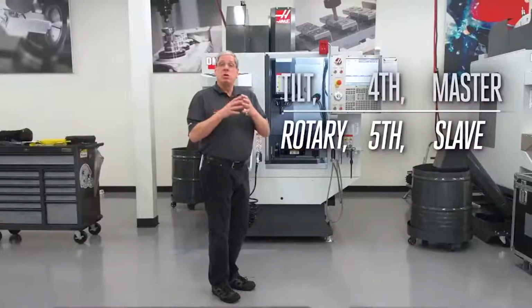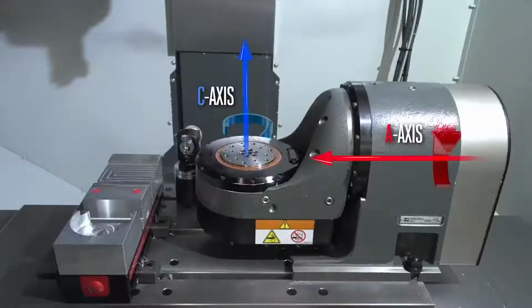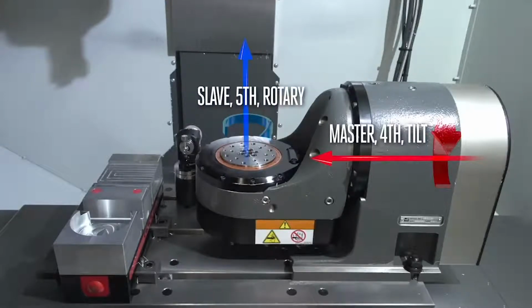These terms come from the fact that the rotary, or fifth axis, is mounted on and moves with the tilt, or fourth axis. That's why the rotary axis is a slave to the tilt axis. So, going back to our TRT-100, our A-axis can be called the master, fourth, or tilt, and our C-axis can be called the slave, rotary, or fifth.